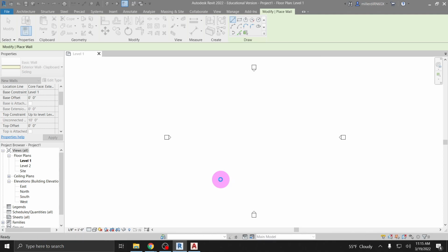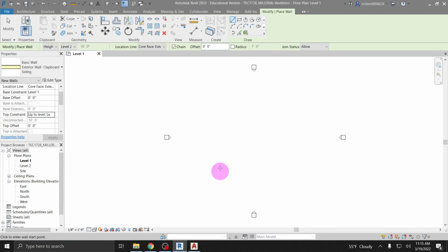Revit's also going to save backups for you quite a bit, which is honestly very handy in case it crashes. So anytime you'll see a file and it'll just be your regular file name, but it'll have like 0.000001, 0.0002. Those are just automatic backups it made in case the software crashes. But so again, you probably want to do clockwise. I'm going to do counterclockwise just to let you know that it's no big deal if you mess up.